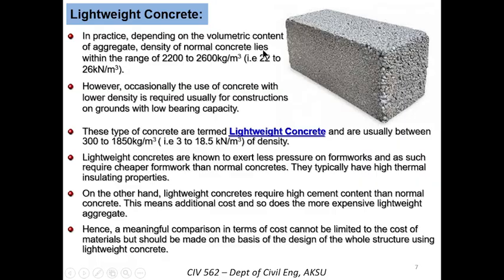That results in about 22 to 26 kilonewton per meter cube. Remember that in our design, Eurocode recommends using 25 kilonewton per meter cube. However, occasionally the use of concrete with lower density is required. You need concrete with a very low density.